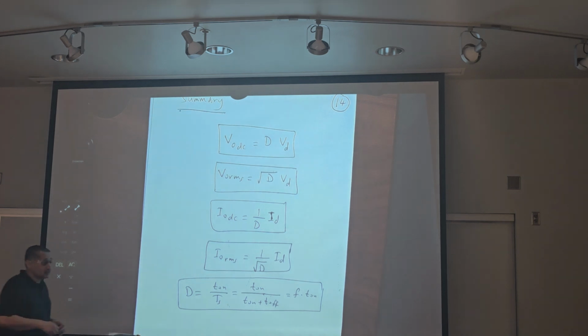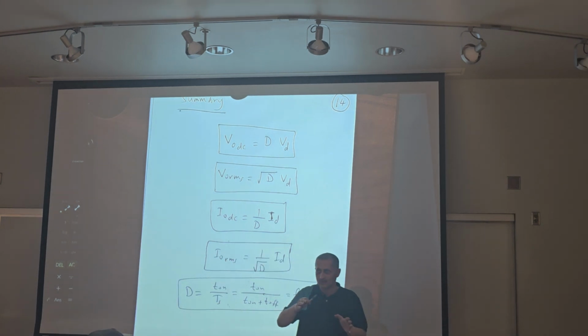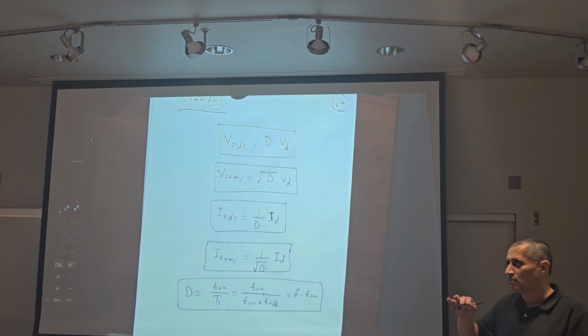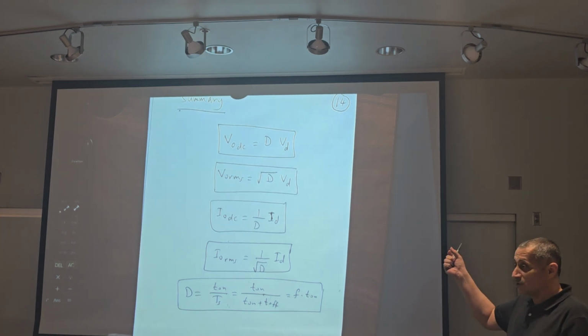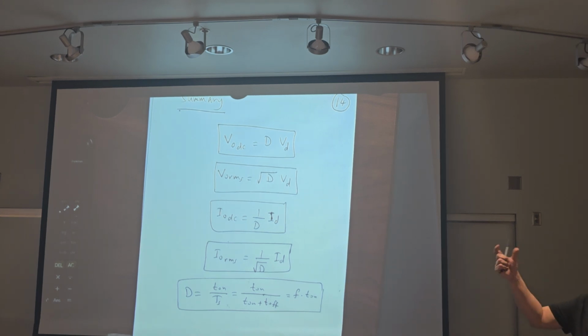The efficiency of the DC chopper, or DC to DC converter, is almost 100%. But if there is any voltage drop across the switch, across the thyristor or transistor, maybe 1 volt, 2 volt, 3 volt, the efficiency drops to 99 or 98, 97.